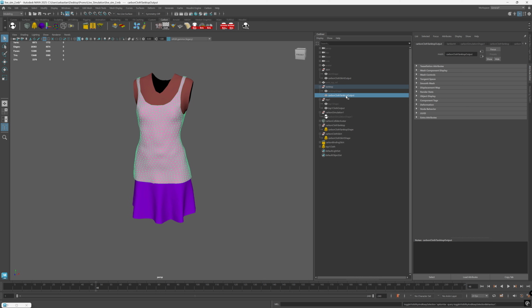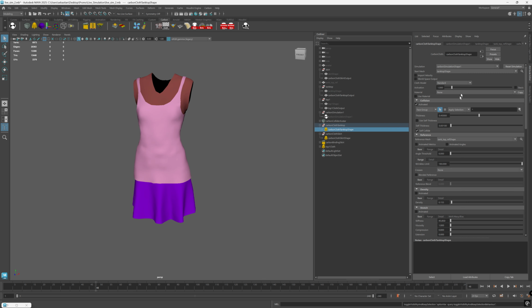Remember, when you see the output mesh not matching the physics draw, there might have been some other accidental deformation or transform or something on the output mesh. You can just delete it, reapply the start mesh to your cloth, and then run the simulation again, and you get a correct output. All right, next up, let's save this out now.